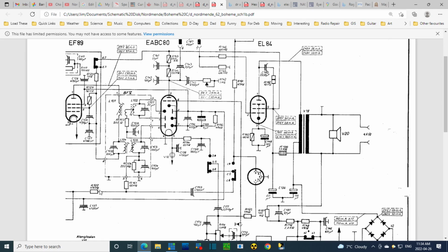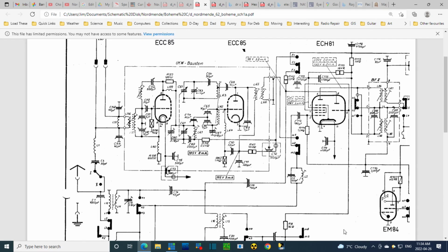I'll look for a fairly large capacitor. We'll go on this side here, and we'll look for a fairly large capacitor. Here's one here. Looks like 0.047 microfarads. It's not terribly large. 0.05. 0.05, yeah, that's typical right here. Yeah, 0.05. So this is the guy who could be in trouble. Now, didn't I change all these 0.05s?